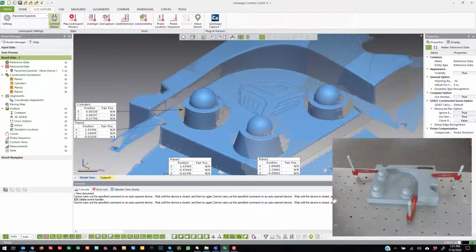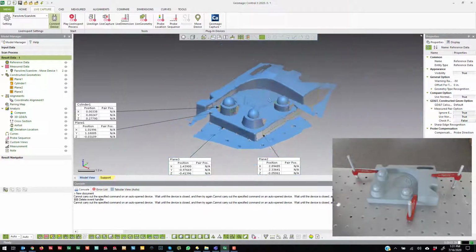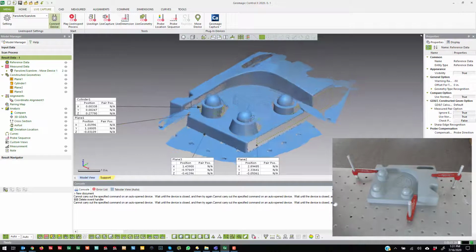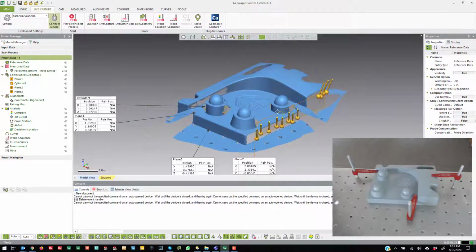Like I could probe these two planes and then actually probe 3 planes here. This one, that one. Intersect all 3 of those to create a coordinate system over here, and that would constrain the position, and then probe this plane to constrain Z. There are just so many different ways you could go about doing it, but these are the building blocks to creating a live alignment.